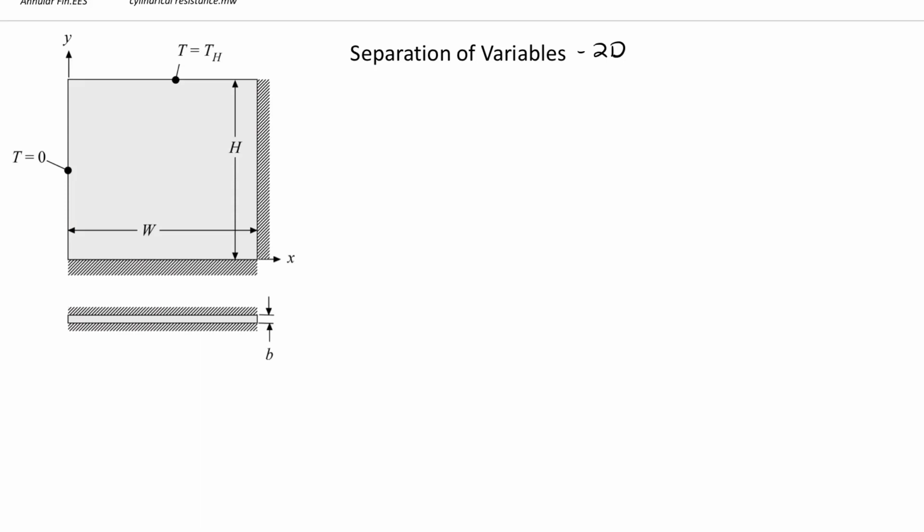In the same way we've started every problem. We're doing conduction. We want to develop an analytical model. So let's first start by drawing a control volume. Okay, so our control volume is now, it has to be 2D. Right, so we're going to draw some rectangle. And it's not covering the full span of any one dimension because, well, it's differential in X and in Y. Okay, so this thing is dy tall, and it's dx wide. Right?